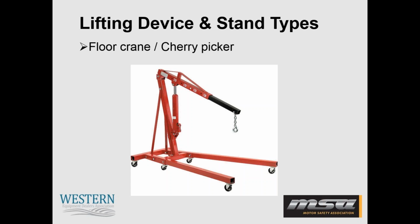And these need to be clearly labeled so that you are aware of that decrease the further your boom is extended. And again, you also just want to make sure with this type of device that you are using the correct chain and hook, and it has a pin that came in here that was originally designed for this machine. I too have seen where people have stuck bolts in to put the chain in, or they've used a different chain that they may have had laying around the shop. So it's important to use the correct type of chain that goes with this type of floor crane at your facility.